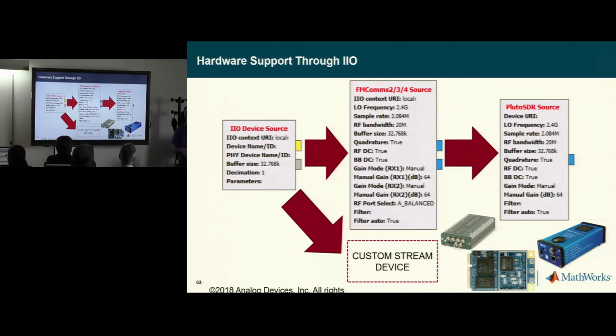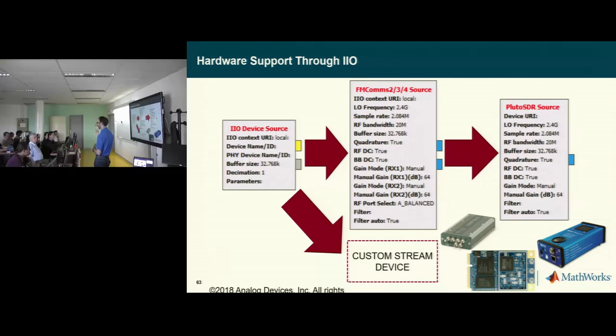Yeah, it's in Pluto today. So if you look at the driver, the cf-ad9361-lpc, the receiver driver, and you list the attributes there, you'll see one that says sample rates. And it will give you 2 options. One that's normal and then one that's decimated by 8. And you just set it to the decimate by 8, and you'll get the lower rate. Since it's in the FPGA, it's a little bit separate from the standard driver, so you need to add this additional piece to get access to it.